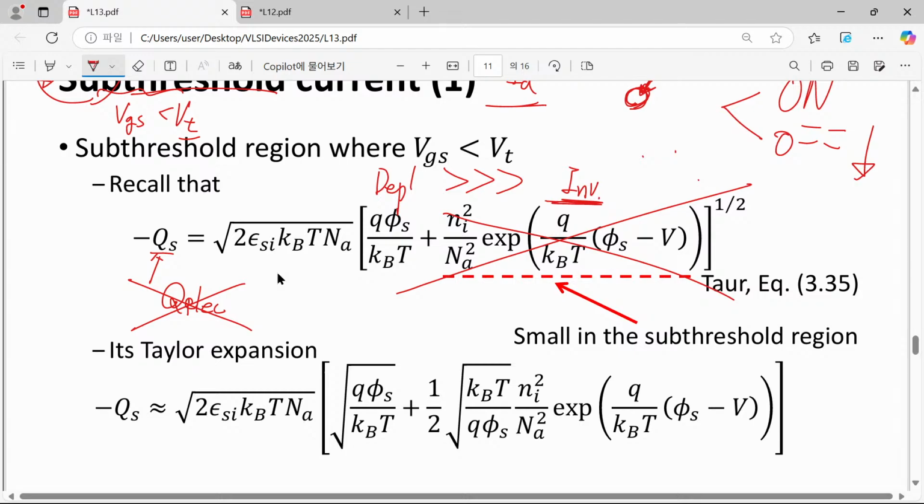That is really the perfect case. But the point is, we wanted to estimate this non-ideal off-current condition. It means that we wanted to apply zero bias to our gate, but also apply a high VDD value to our drain and try to measure the current.